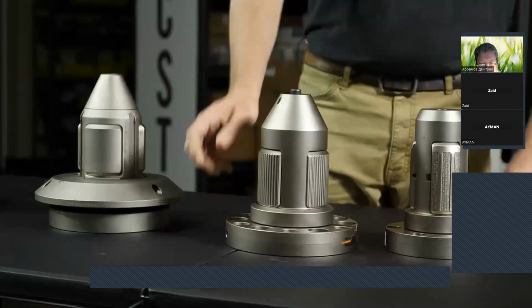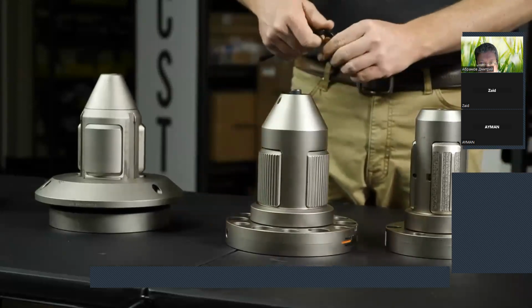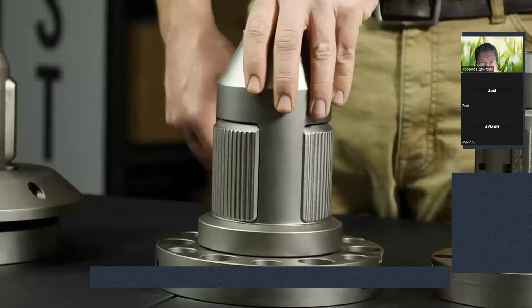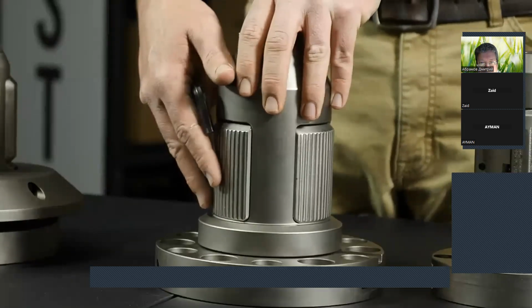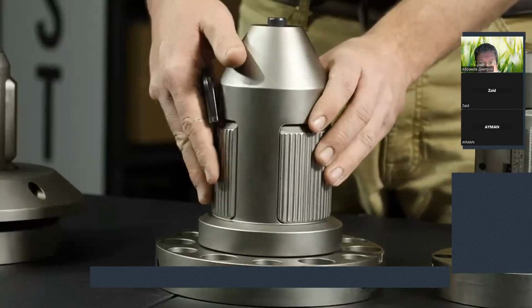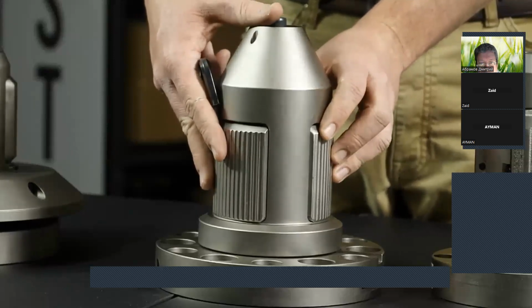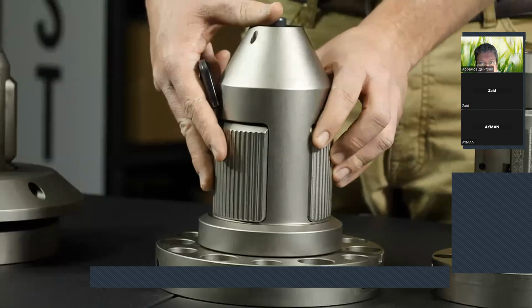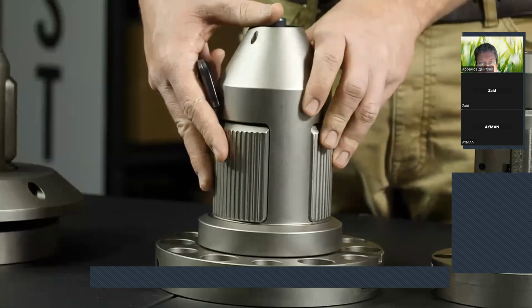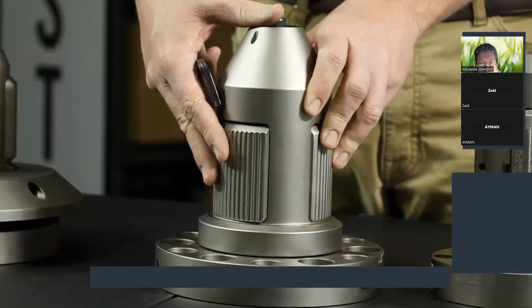Let's have a closer look at some of the chuck's remarkable features. Our standard jaw design features serrated expansion units. So by implementing the serrated jaw and creating an extra large contact area with the expansion units, we can easily grip worn and recycled cores. This means we can reduce slippage and dust and core debris created by core slippage.